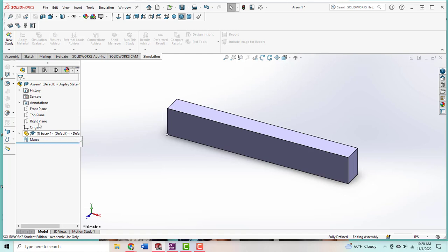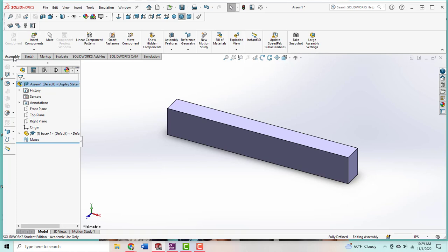As we build these different parts for our assemblies, you're going to notice that as we bring them in, the parts are going to be listed on your Feature Tree Manager. You can hit this flyout arrow and it's going to show you the features and how that was built. So you could select the origin here, the origin of your assembly, and add in a coincident relationship if you are not attached to the origin. But as long as you just select the green check mark for your base component, it's going to attach it to that coordinate system.